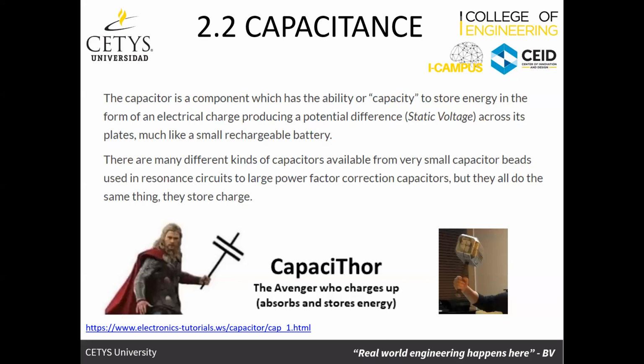That's actually a good question, and that's why it's important. In the servicing of electrical equipment, there won't be things on the electrical board that tell you. The capacitors are going to be there, and you won't know if they're charged or not. There's nothing visual that will tell you. You would need to literally measure it.